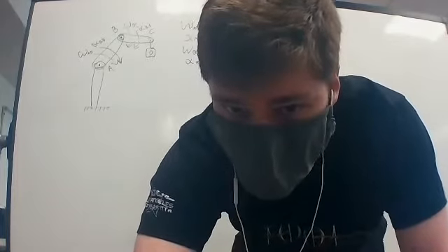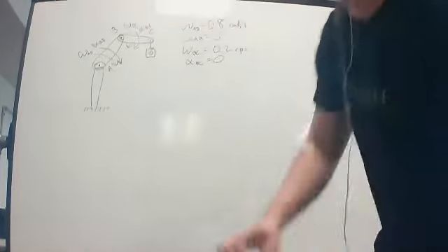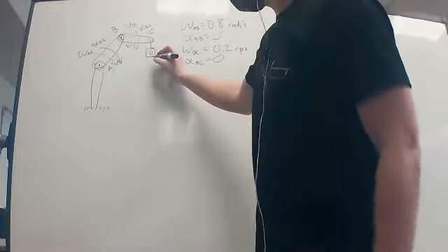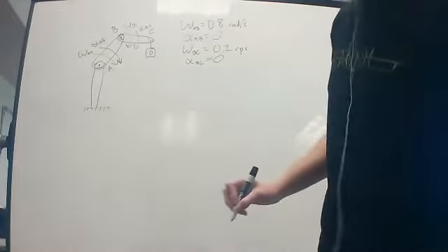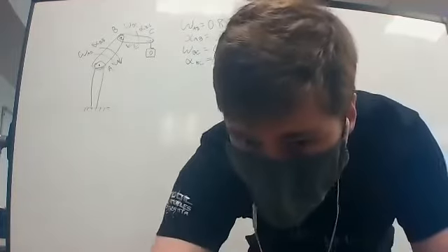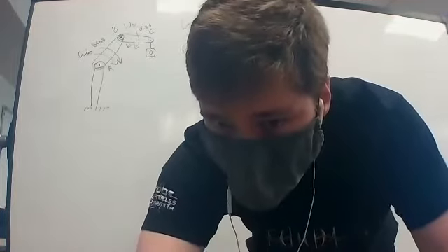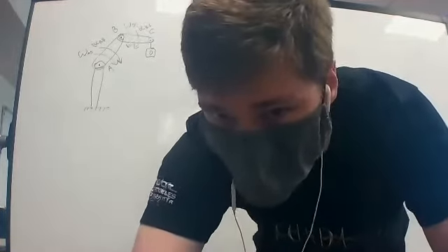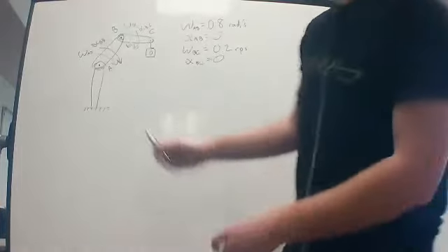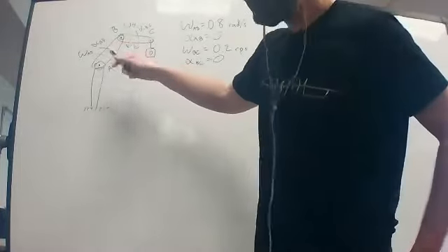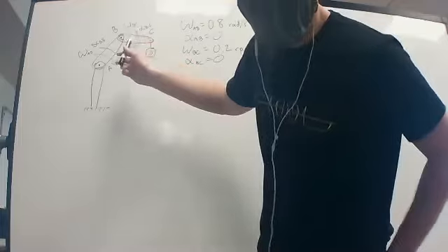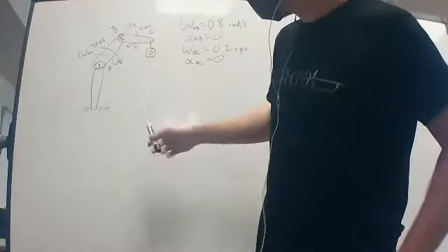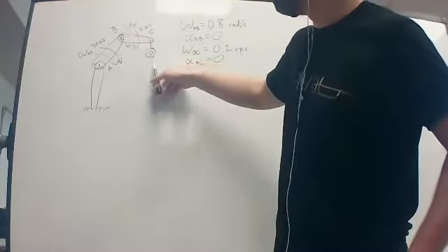We are asked to find the acceleration of part D. So we're looking for acceleration at D. So we can go ahead and classify motion. We're going to know that AB is a rotation about a fixed point, BC is going to be a general planar motion, and then D is going to be translation moving straight down.